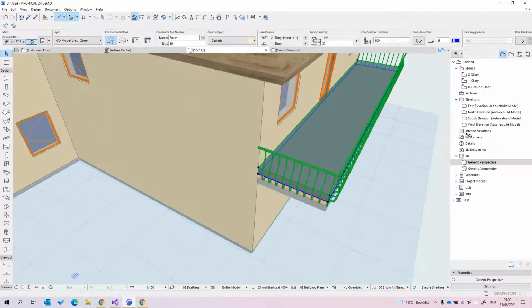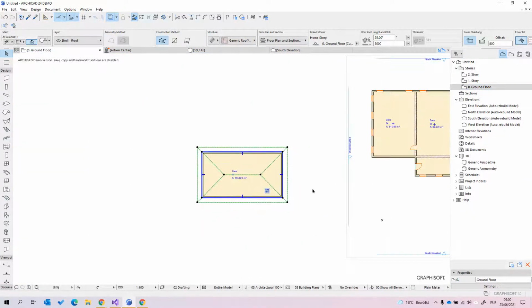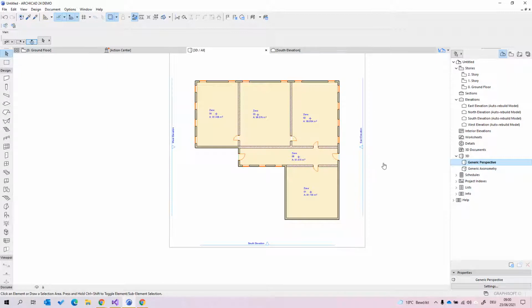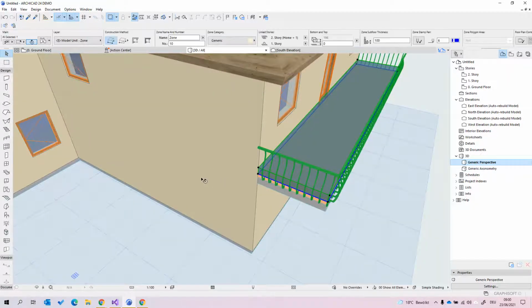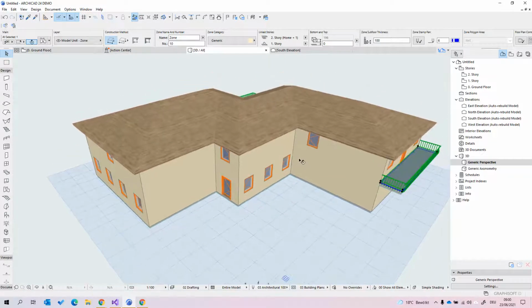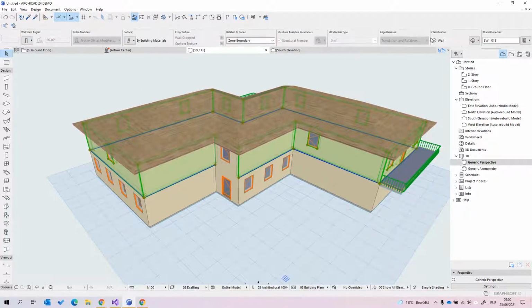Now, let me go ahead and delete the object that we created here, and show you how the GbXML export from this particular model will look like at CAALA. So before we go to CAALA, let's just review how each floor is tagged or each element is tagged. So let's look at all the external walls. You can see all the external walls need to be tagged CAALA A01.